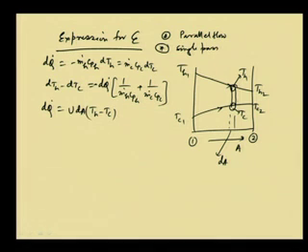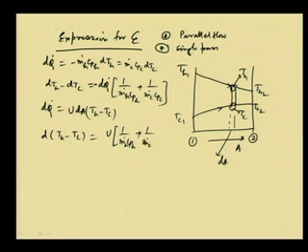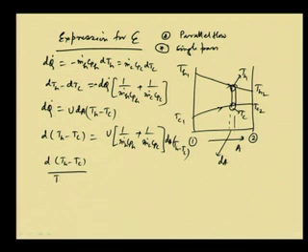For the small differential area we assume it is uniform. Therefore, we can write that d of Th minus Tc will be equal to U into 1 by m dot h Cph plus 1 by m dot c Cpc into dA into Th minus Tc. So, therefore, we can write d of Th minus Tc by Th minus Tc.